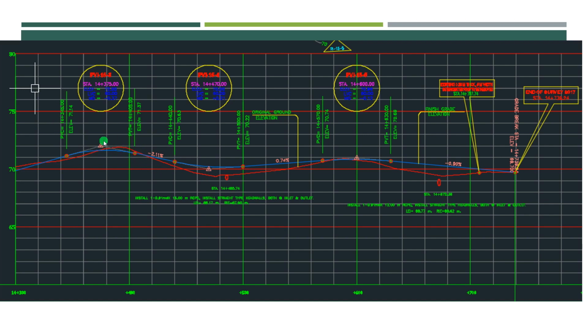These tangents have slopes. It is given here, negative 2.11. It should be identified because it is important that the slope of the tangents shall not exceed the prescribed maximum slope in making a roadway. Depending on the country, there is a maximum slope that should be followed in designing the profile or the alignment of the roadway.